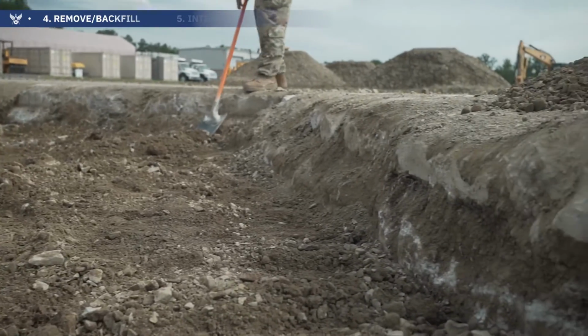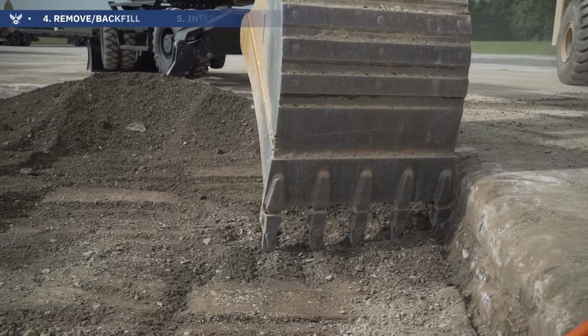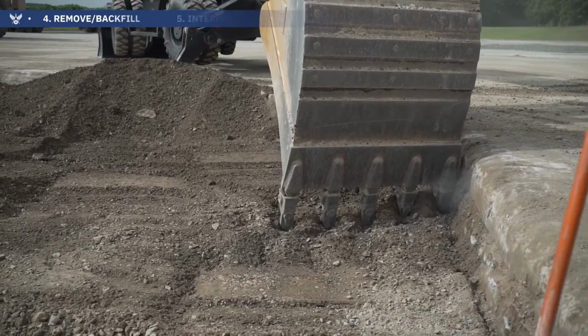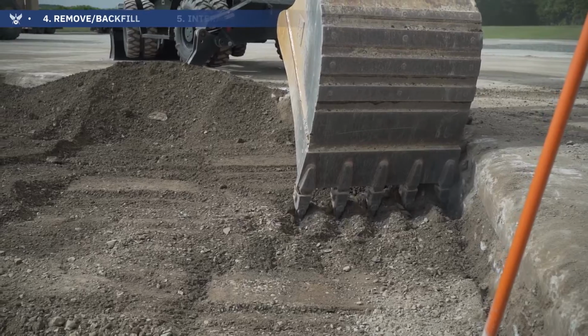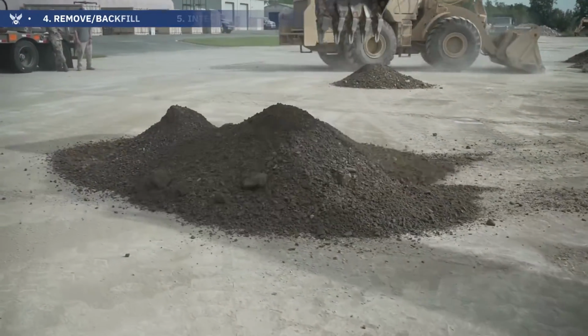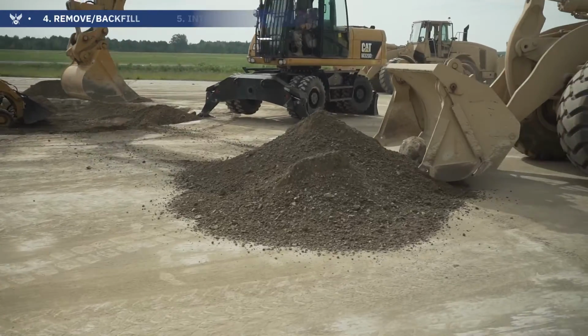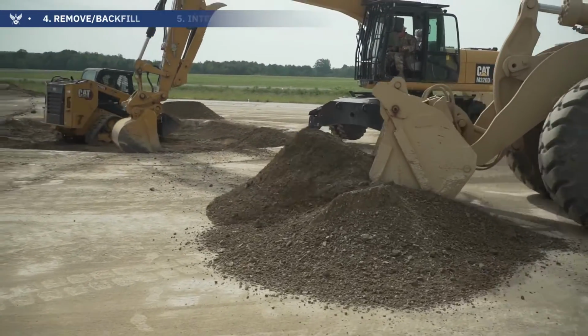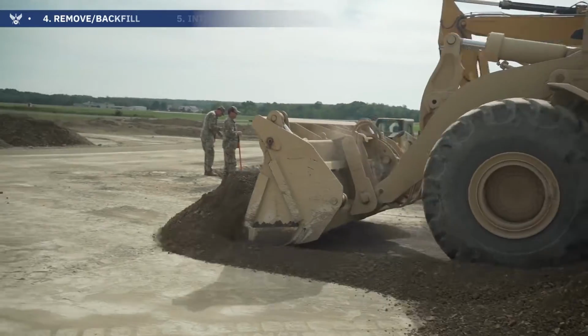Using the excavator moil point, break up the upheaved pavement not removable using the excavator bucket, or whose removal will cause the crater to become too large. Push the unusable debris to at least 30 feet off the MOS and pile no higher than 3 feet.